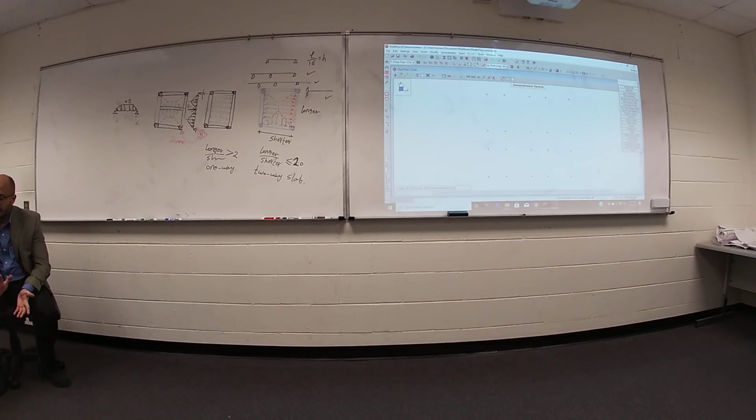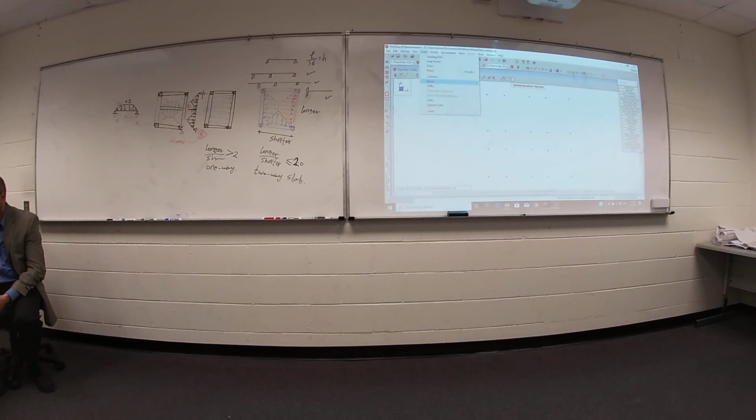Any question? Second, we need to define or draw your beams. Anybody remember how I can draw a member? Insert, remember? Insert beams. So right now we have beam and we have column. In RISA 2D we have only one member. Member may be a column or may be a beam. But here we have different names. So insert beam.